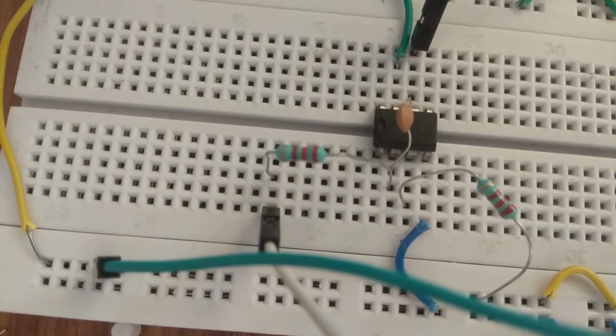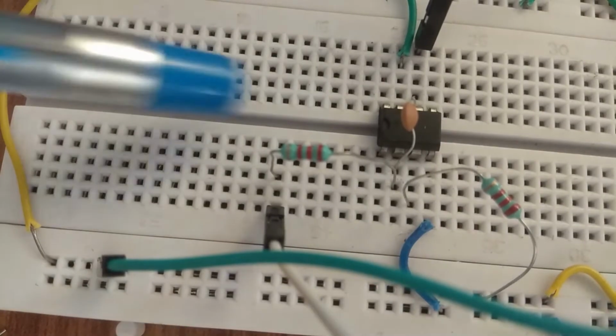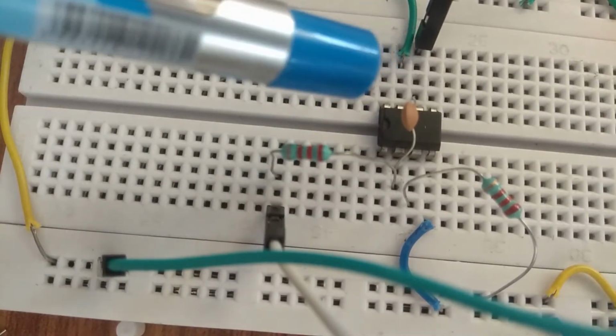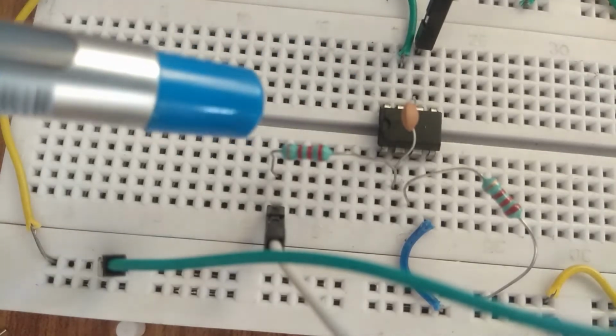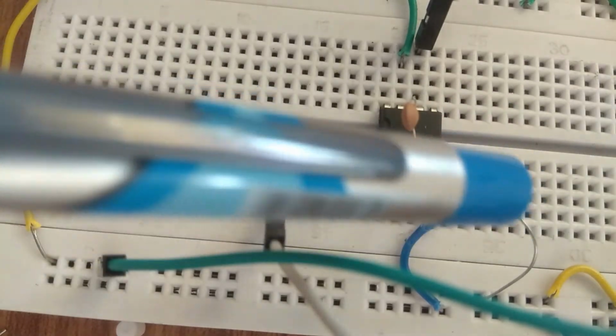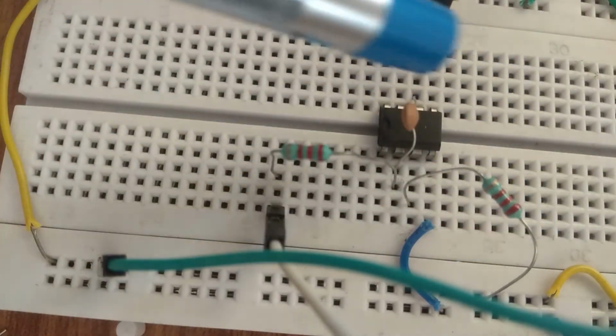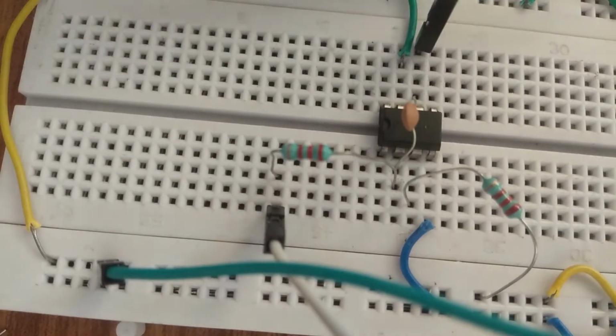Now if you see, this is the circuit. This is the biasing I have done, with the green wire the positive biasing and the blue wire the negative biasing. This is your op-amp, and this is the feedback capacitor, 4.7 nanofarad, and this is your 2.2 kilo ohm. This is for nullifying the offset voltage, connected to terminal 3. Here we are supplying the input, and from here we are taking the output.